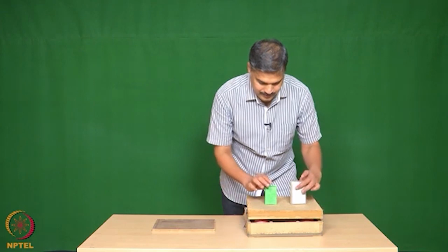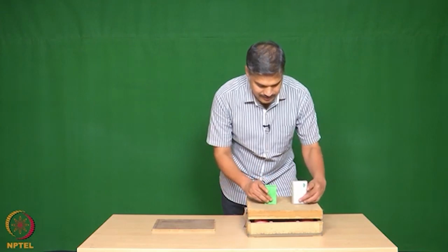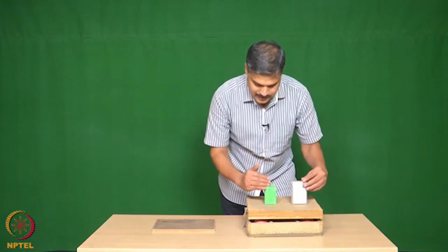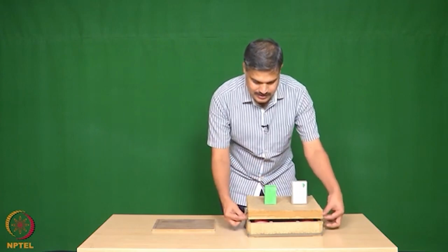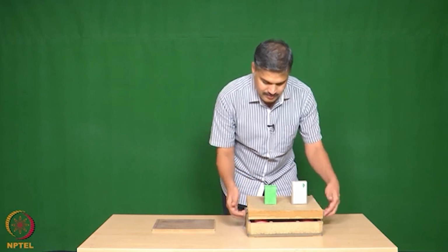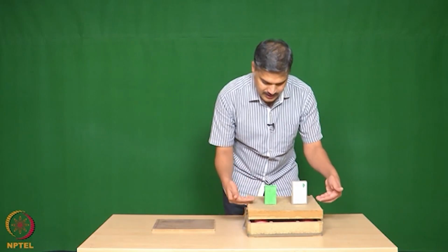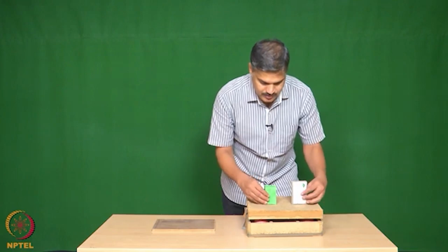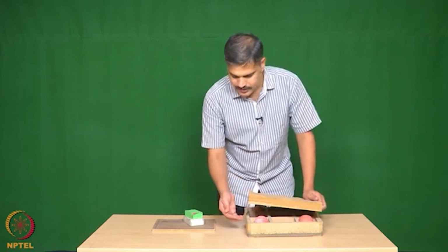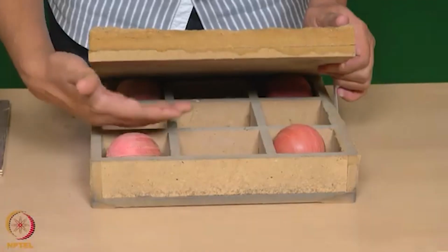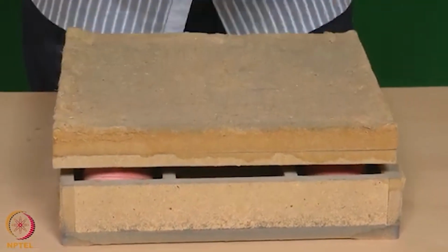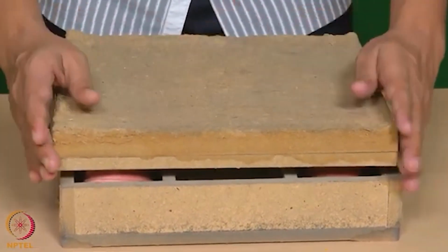We have to evaluate the natural frequencies of the building and then design the bearings in such a manner that those frequencies are eliminated from the ground motion which is entering the building. So this is called base isolation technique. We are isolating the frequencies which will harm the structure. Those frequencies will not enter the structure, and that technique is called base isolation technique.